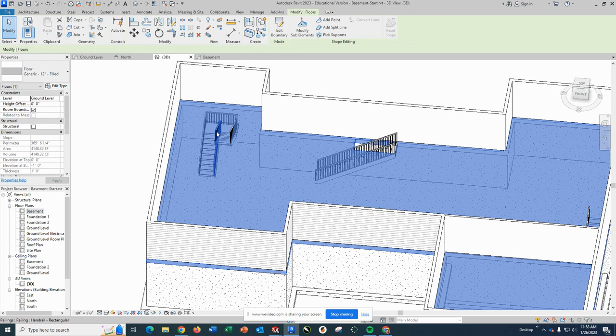I know it's not realistic in a house, but I do want you to put in all 3 types of staircases. And at all 3 different types of staircases, I'd like you to mess with cutting the floor, making sure you have enough head clearance for coming up, putting interior walls around it on the ground level, interior walls around it on the base level, and I will have you use some screenshots of those various staircases to show what you did. And don't forget, you can always select the floor and it'll go blue and kind of transparent so we can see through it as needed.